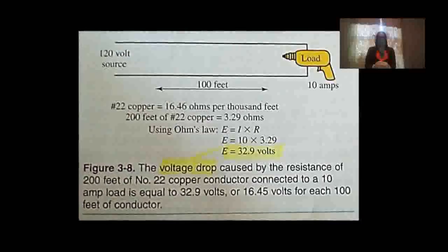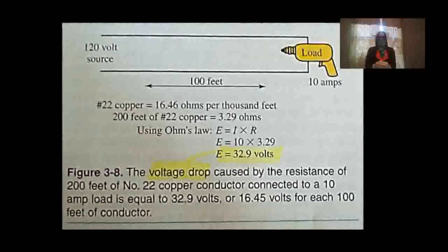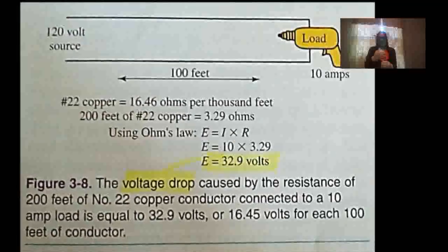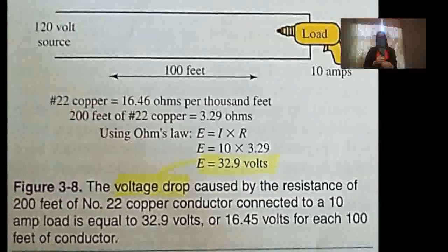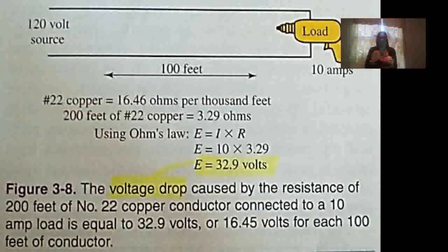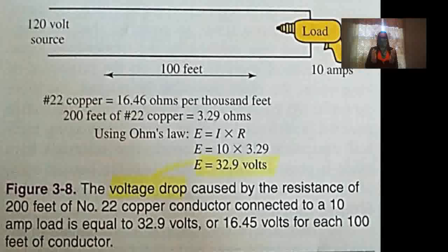Length of conductor. The length of a conductor greatly affects its total resistance. If 1 foot of wire has a certain resistance, then 10 feet of the same wire will have 10 times the resistance. 50 feet of the wire will have 50 times more resistance, and so on. As a conductor becomes longer, it creates a voltage drop in a circuit. A circuit using short lengths of wire, such as an electrical lab project using 3 to 6 inches of number 22 wire, does not create a major problem, but long runs of wiring can create electrical problems.